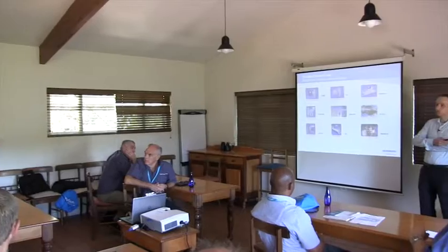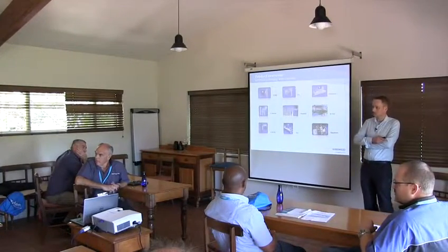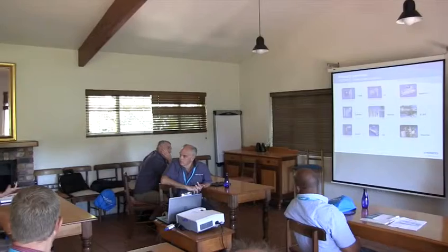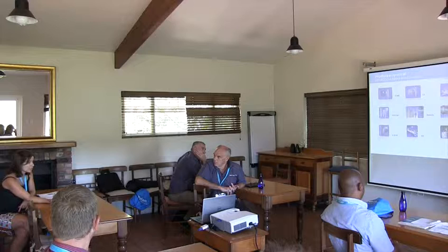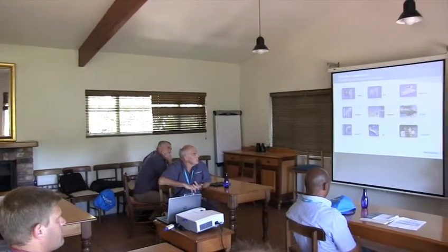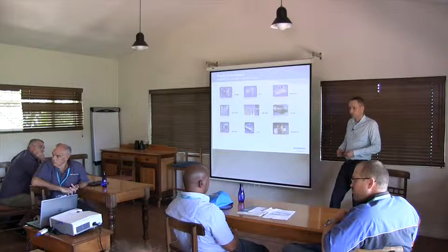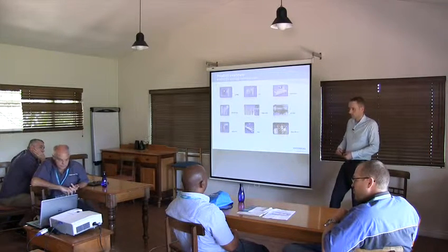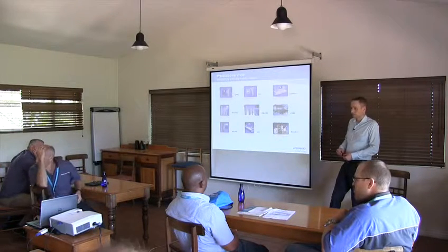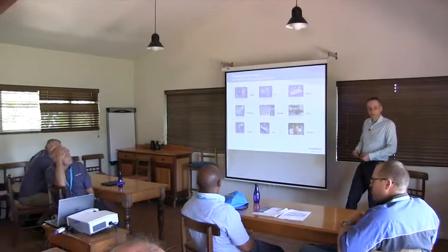But what I just want to mention is suspended solids and UVT and all those things. Our systems can handle a UVT of down to about 30%. And even suspended solids up to 30 or 50 milligrams per litre, depending on what you are looking at. For wastewater, it depends on the effluent quality you have to achieve. It's just going to be more expensive, and you're going to have to use a bigger unit. So it's going to be more cost effective to have better quality water prior to UV. If you can't do that, we can still treat it, but it's going to be a much bigger, more expensive system.